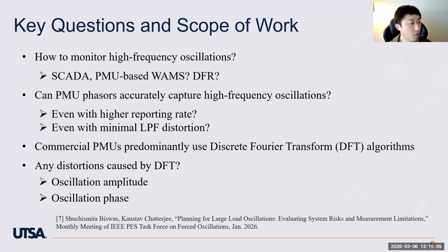How to monitor high-frequency oscillations? Based on existing infrastructure, we have SCADA, and we have the PMU-based WAM system. Those stream data into the control center. We also have digital fault recorders doing high-speed measurements locally at the substation level, with or mostly without streaming to the control center.